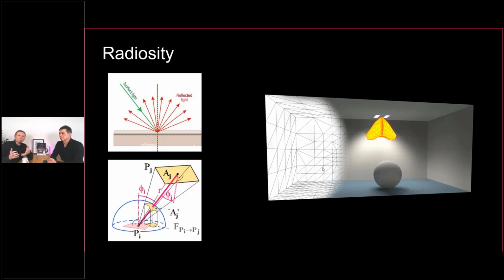The surface of the room has a big impact on the results, especially on uniformity. And here you need to have, as best as possible, the surface properties in terms of reflectance of the walls and of all the objects in the room. And this is the big difference also between calculation applications. This is the indirect part. And we have in RELUX a lot of options where you can set the indirect part to more accuracy.